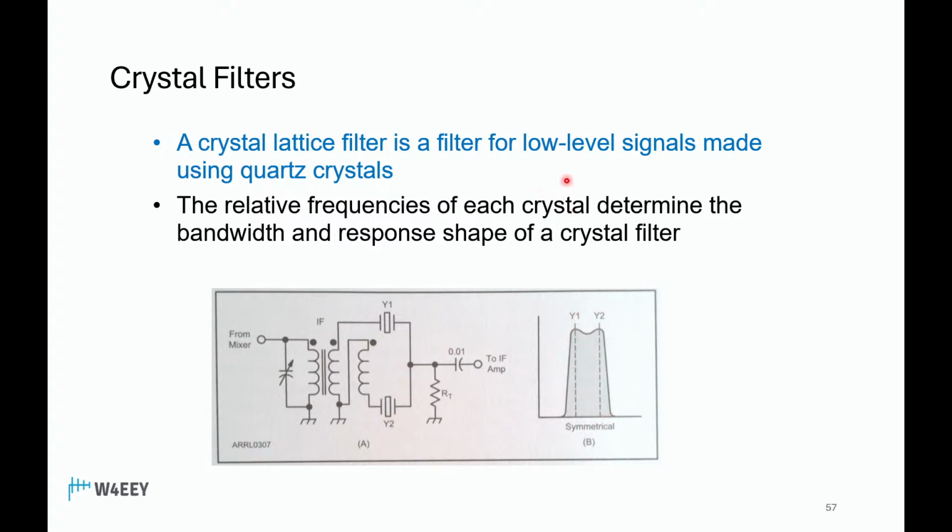Now it says low level. This isn't something we're going to be filtering transmit signals. We won't be putting watts through these. We'll be putting in microwatts. The relative frequencies of each crystal, two shown here, will determine the bandwidth and response shape of that filter.